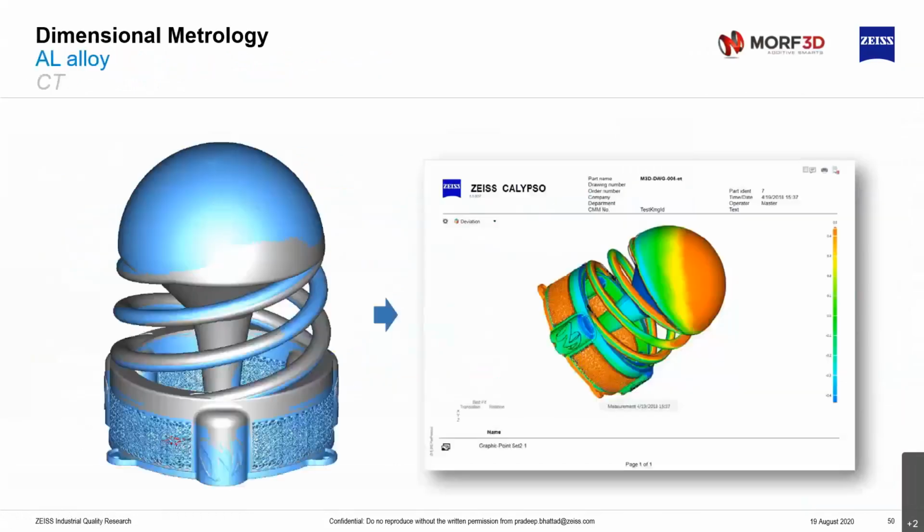And the last part is basically as we start creating more and more complex materials with additive manufacturing, measuring those parts becomes extremely challenging. So how do you measure these free-form surfaces or extremely complex geometry like lattice using traditional methods? In that case, traditional methods may not be applicable. So what we have done is develop these metrology capable CT instruments, which allow you to take the CT image of the part and measure internal, external features, similar to the examples I showed you in the heat exchanger.